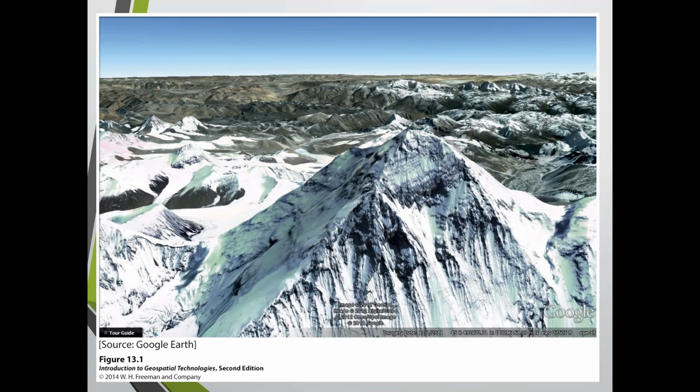So you can take that digital terrain model and use it in, say, Civil 3D. What we're looking at is the digital terrain model with what's called a drape image on top of it. So you're actually looking at basically a photograph that has been draped on top of this. Your digital terrain model would be like your framework underneath. If you strip that image away, it would just look like a normal TIN, which is what it actually is. So again, this is just in normal everyday Google Earth software.